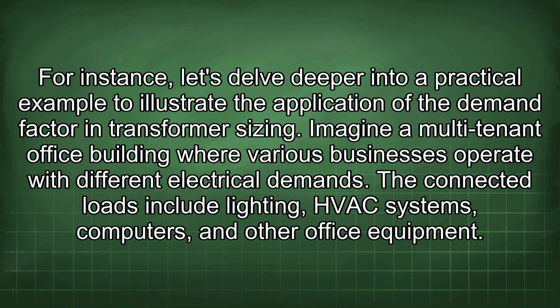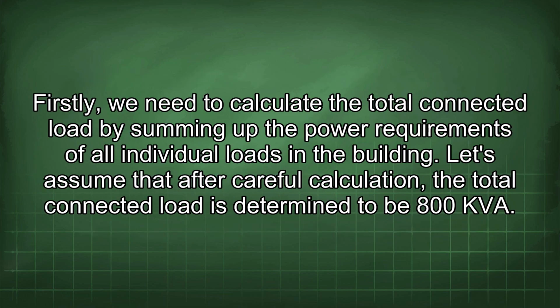For instance, let's delve deeper into a practical example to illustrate the application of the demand factor in transformer sizing. Imagine a multi-tenant office building where various businesses operate with different electrical demands. The connected loads include lighting, HVAC systems, computers, and other office equipment. Firstly, we need to calculate the total connected load by summing up the power requirements of all individual loads in the building. Let's assume that after careful calculation, the total connected load is determined to be 800 kVA.